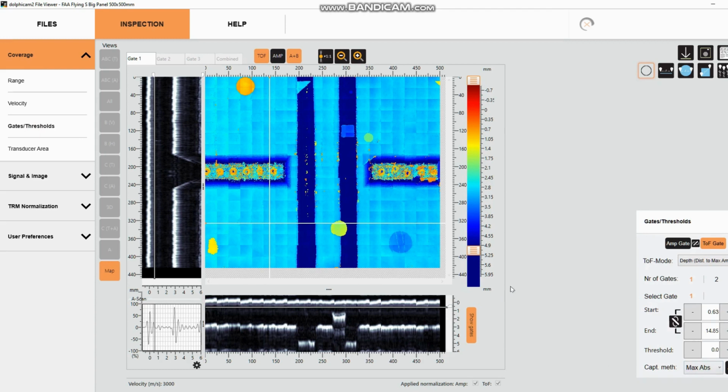So there's two ways to improve this. First of all, right now I'm measuring from 0.0 to where I pick up this echo here, and have my gate here set past the penetration echo, and I'm picking up maximum absolute value, which in this case is positive.